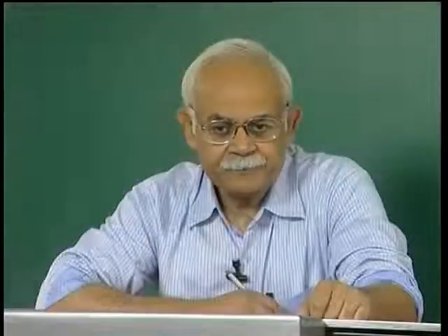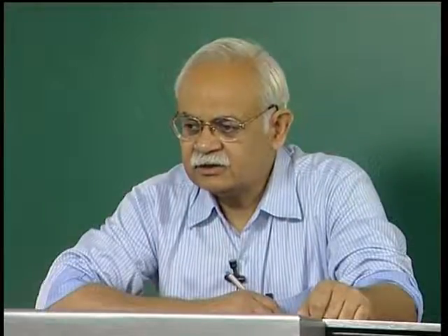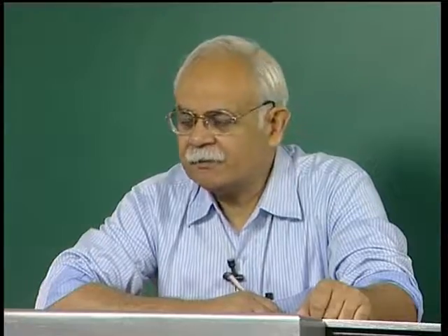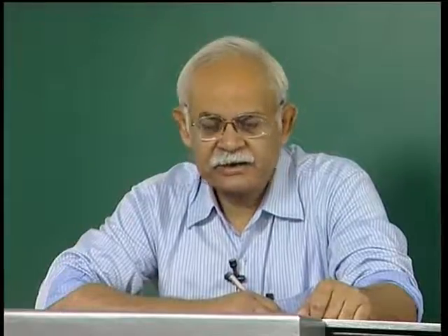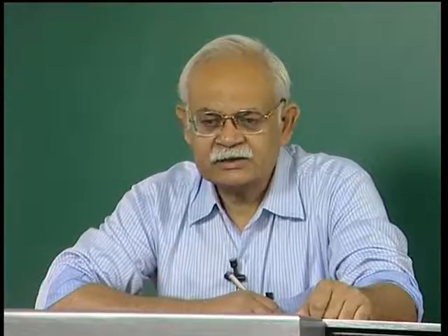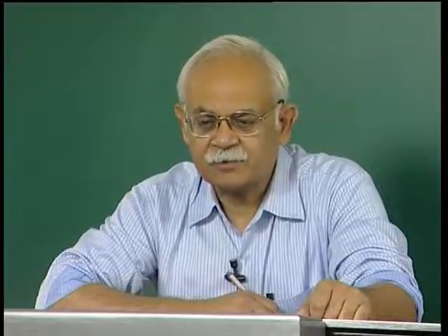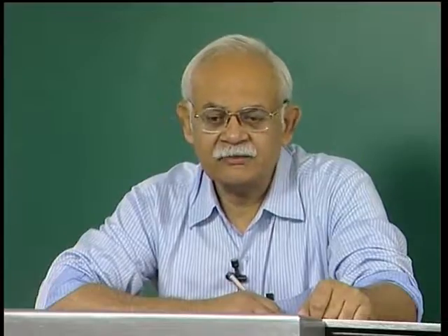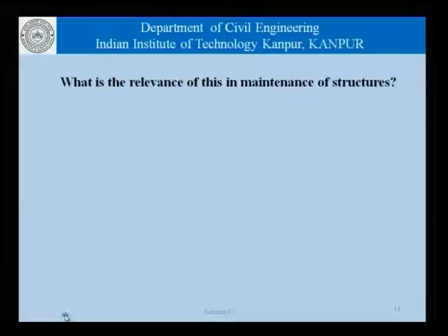We must also remember that the design specifications are not time independent, they are time dependent. That is, specifications change over a period of time. A code published today may permit a certain amount of deflection, and that gets revised when the code is published 10 years later. The designer understands these things, and the problem arises for structures which were built for a different set of specifications.